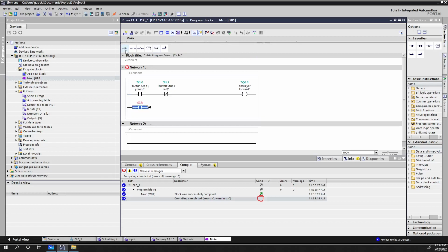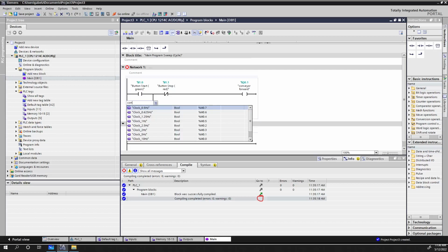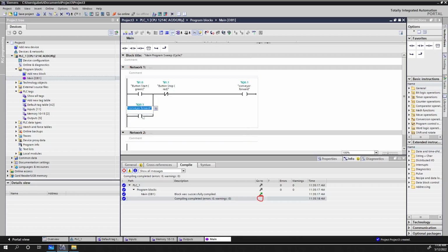And then I put another make contact in, and I click the up arrow. It takes me there. Now, if I didn't want to use that up arrow, I want to cover both of these, I can click and drag, and it shows me the gray boxes where I can drop this. For my purpose, I want it around the start button. So I can put conveyor forward here again, on an input symbol. It's on an output symbol. And now, anytime that the conveyor forward is true, this will also be true.